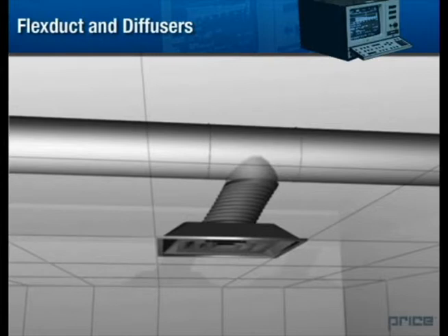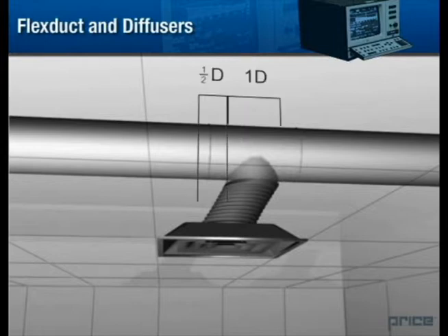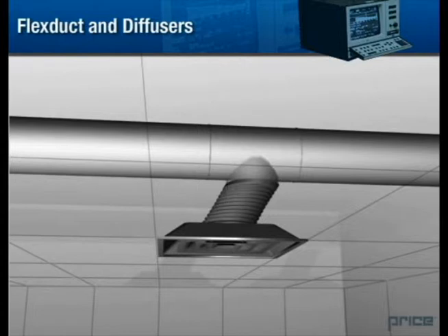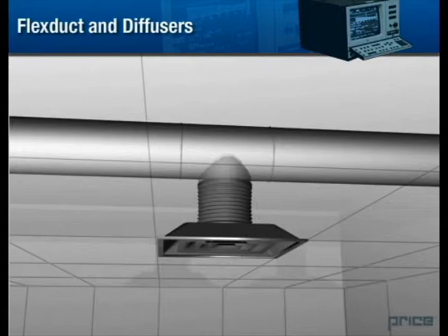Scenario 2. Improper installation of flex duct. Another factor that can contribute to poor noise levels in a room is the improper alignment of diffusers to the supply ducts, especially when flexible duct has been used in close quarters. Skewing or crimping the flex duct by half a diameter can add up to 15 decibels to the manufacturer's noise rating. By placing the diffuser directly under the takeoff and straightening the flexible duct connector, noise levels can be minimized.